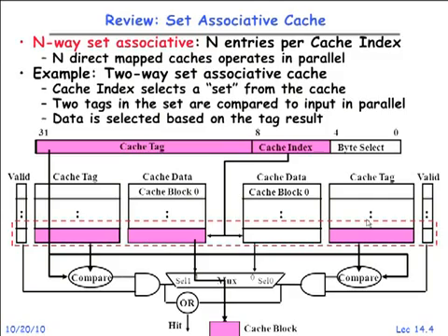You can flush the processor pipeline if it turns out you miss. Whereas with any associativity higher than 1, which means not direct mapped, you've always got to do this comparison first and then use it before you can use the data. So at minimum, direct mapped avoids these muxes to the data value.